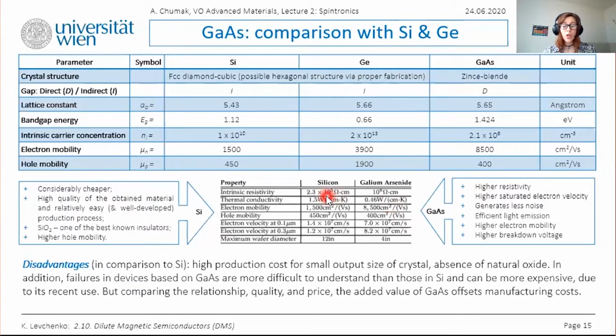What does it mean? A high electron mobility means that you can shoot electrons across the transistor faster, get a higher gain and higher bandwidth of transistors, get a better conduction with a lower doping level. And lower thermal conductivity means that the material conducts less heat.